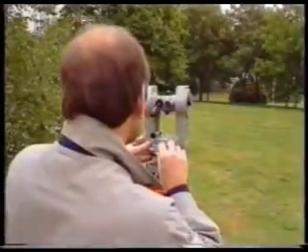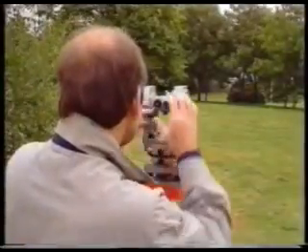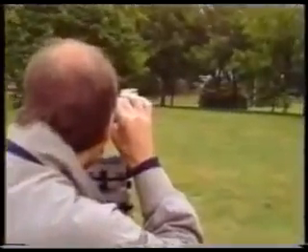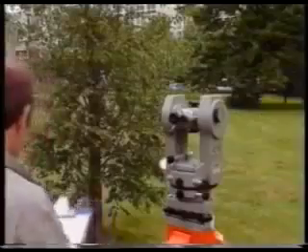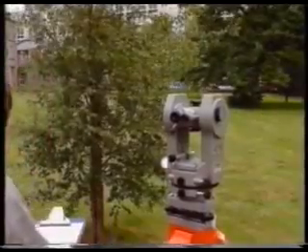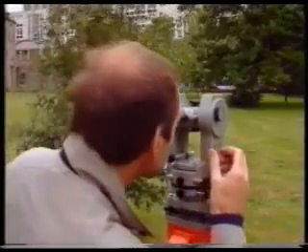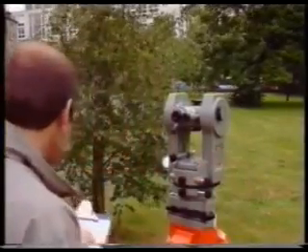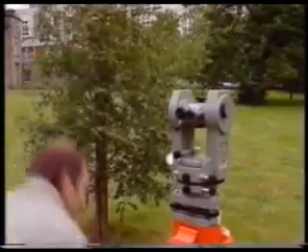Once the theodolite is correctly set, and before any of the points of detail are fixed, an observation is taken to another control point, B. The horizontal circle is read and recorded. This establishes the orientation of the circle and is used later when plotting the detail points on the plan.